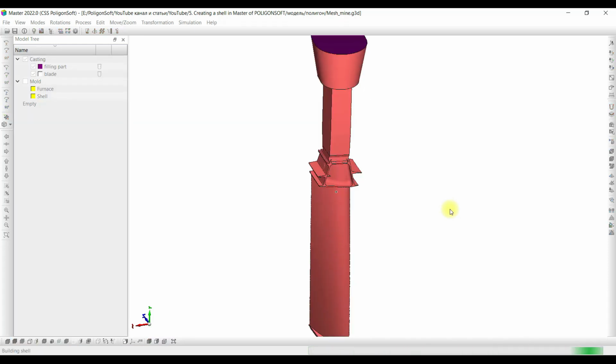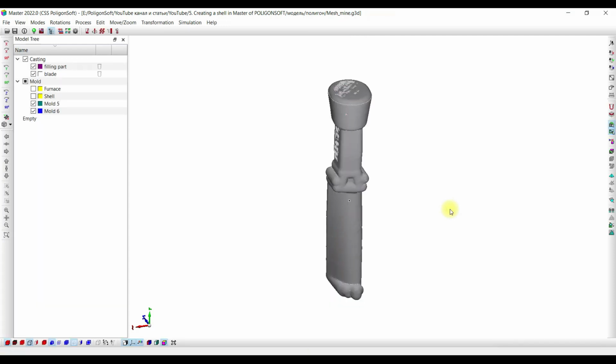The program is now making a copy of the volumetric mesh while removing the surface mesh. Next, the program checks the quality and cleans the bad elements, and then the model is sent to the Salome mesh model to create a 3D mesh. The shell has been created.